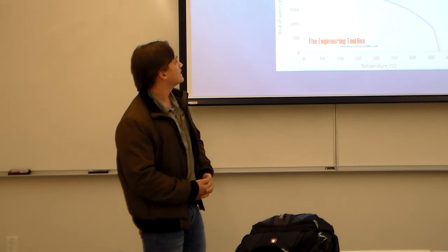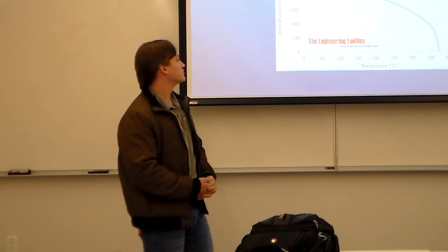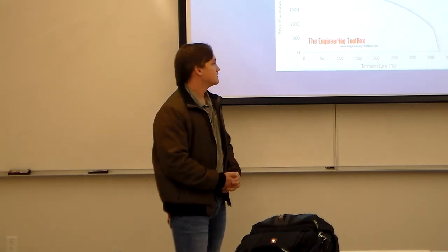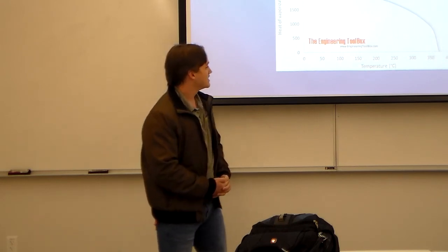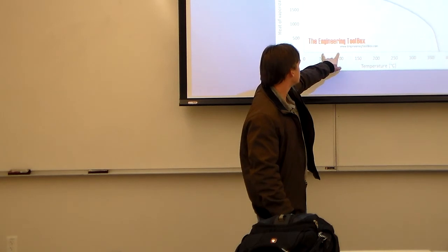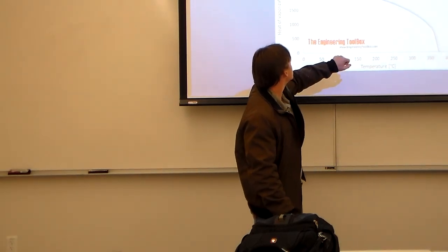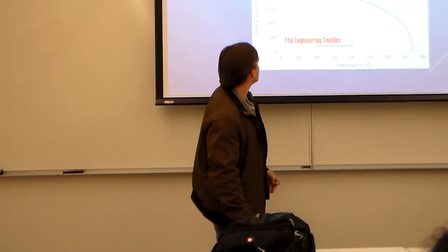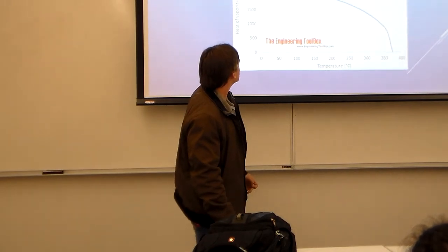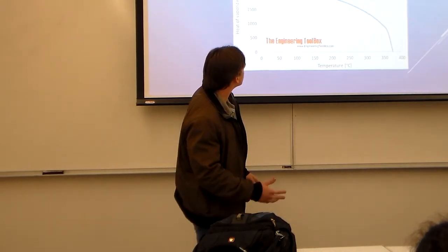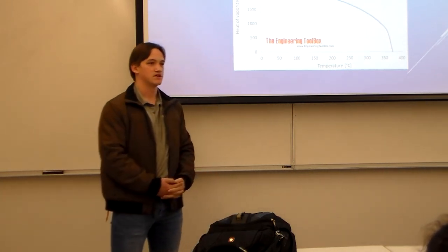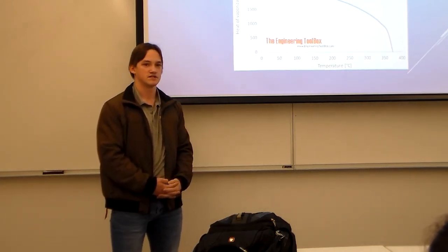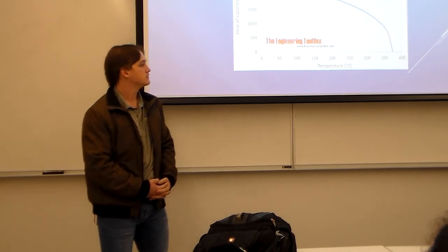Here is a latent heat of vaporization versus temperature chart. Pretty standard, pulled it right off of Google. And we'll be testing around the 50 to 100 range right here. So we should be expecting about 2,300, 2,400. And we should be able to confirm that with our thermodynamic tables as well, as stated.